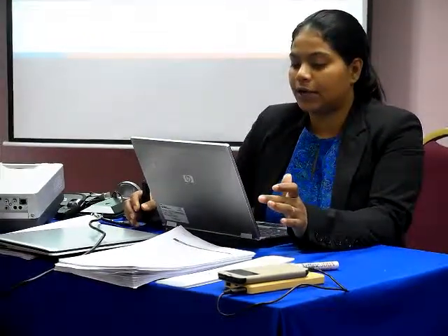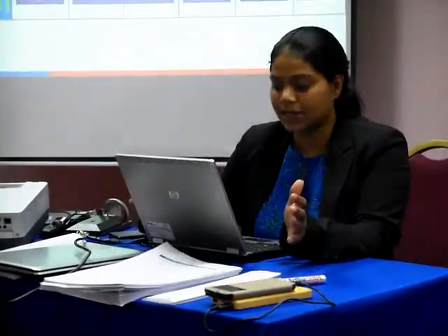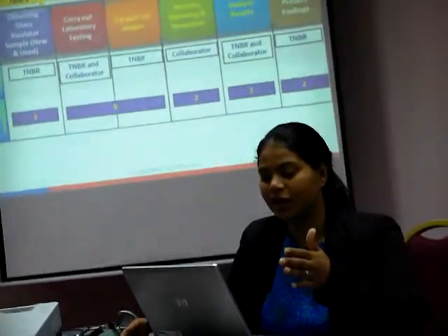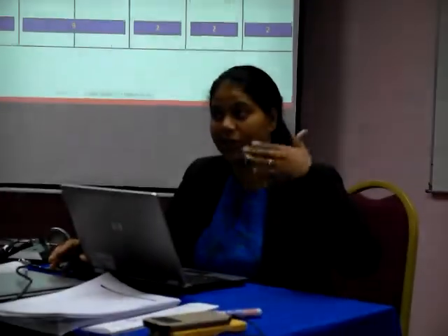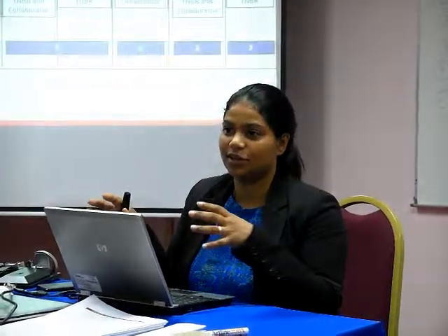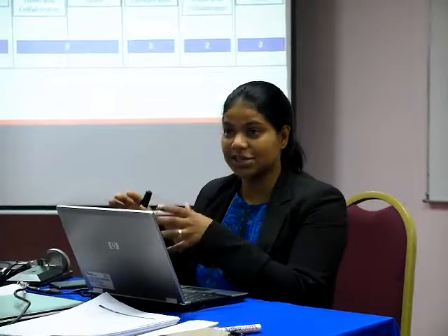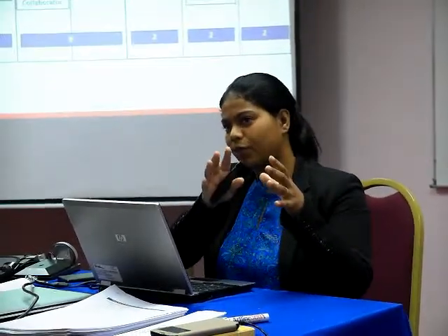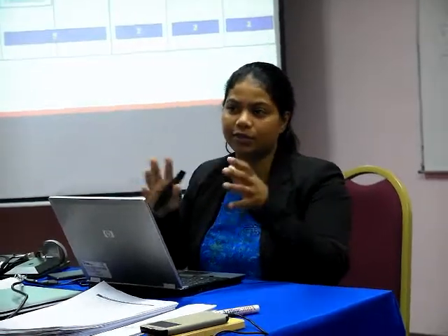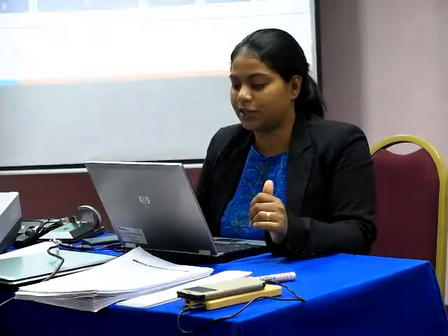So first of all, we will obtain the glass insulators from site, and also we will purchase new glass insulators. This is for comparison. And we will carry out laboratory tests. We have the new ones, we have the aged ones, degraded ones at different levels. And while the accelerated aging or the laboratory test is going on, we capture these UV images. When we capture the UV images, we will probably group it or tabulate the results. So we can classify them into groups.